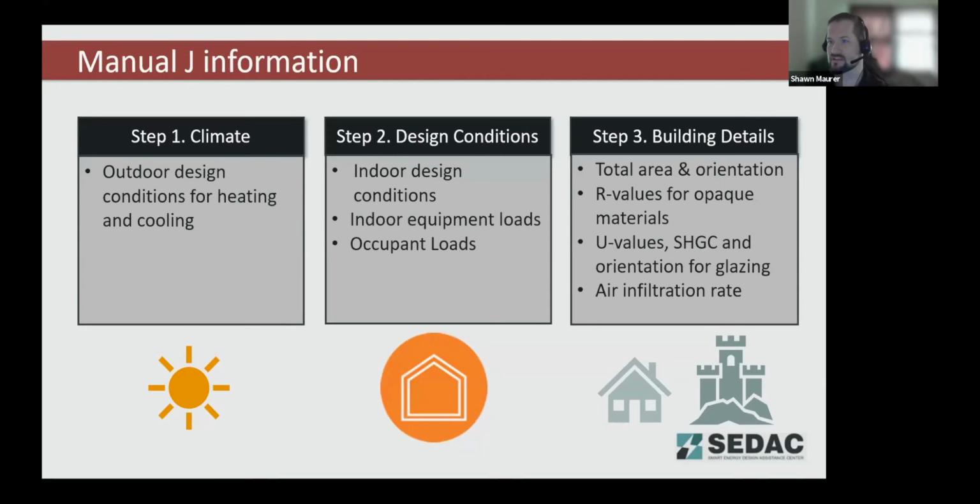What are your insulation levels? What are the surface areas of the building? Air infiltration rates, duct leakage rates, all that information. So most of this presentation is going to focus on that step 3, but probably step 1 is the most important part. Making sure that those temperatures for design are the correct design temperatures. And even step 2, those indoor design temperatures can have a big impact on the load calculations if they aren't properly selected.